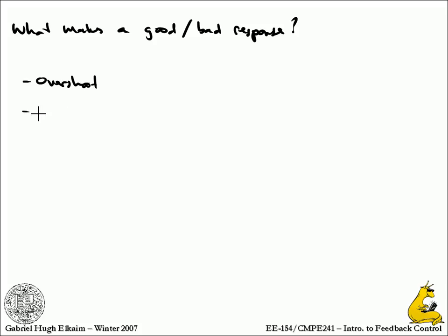What are some other ones? Rise time. If I want to point at the star, and it says, give me about 3 hours, I'll get there, you're like, okay, that's nicely damped, very clean motion, but I'd like to get there today, not next week. You have small overshoot and a small settling time, if you can, but what you'll find is you are limited.